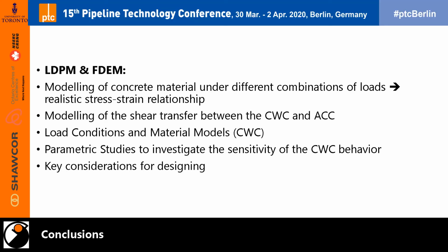And for the conclusion, LDPM and FDEM were successfully calibrated and validated. Modeling of concrete material under different combinations of loads predicts a realistic stress-strain relationship, which is really useful for designing CWC. Modeling of shear and transfer between the CWC and ACC is very important and can be simulated with these models.